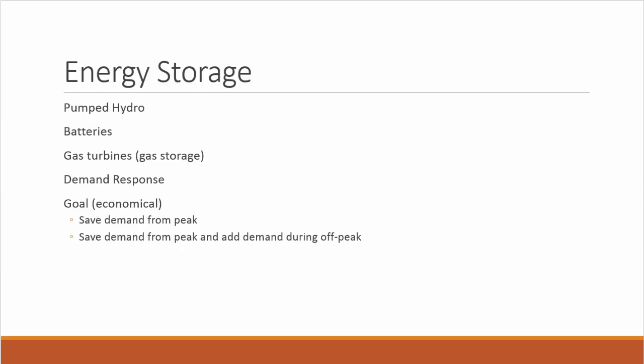Another area with transactive energy that is very interesting and appropriate right now is demand response, where the end-use customers could be pulled so that their heavy use appliances, such as air conditioners, most importantly, and refrigeration, could be turned off when the system is in stress, such as frequency deviations or voltage deviations, and therefore enable the system to remain stable. And it is this area that I have been most interested in for at least 2 decades.